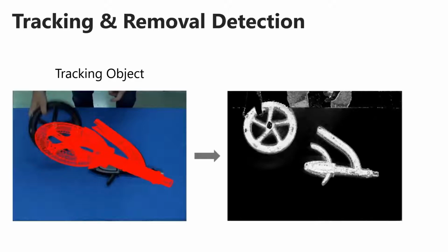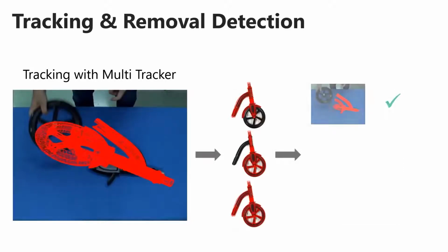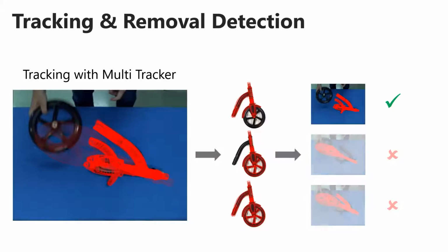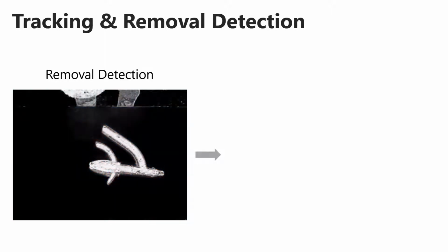To improve tracking stability, we make use of the previously determined removable parts list. We use multiple trackers, one for each removable part, and use the tracker with the highest confidence, that is the one tracking a still attached part, for pose tracking. We infer the removal of a part from the probability of its 2D projection. Therefore, we project each removable part to image space to generate its footprint using the current assembly pose.